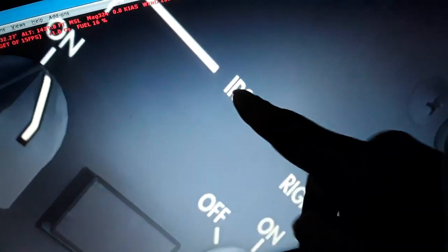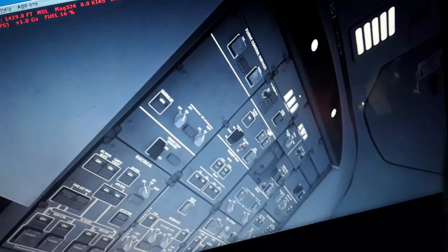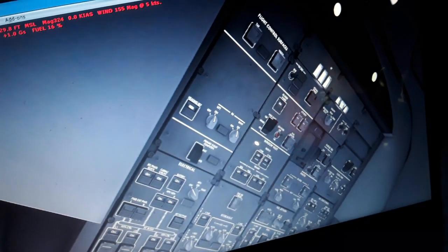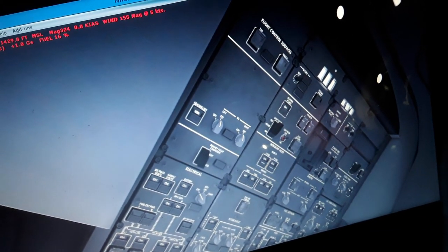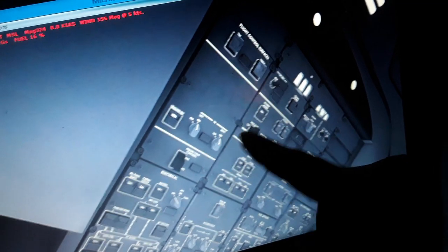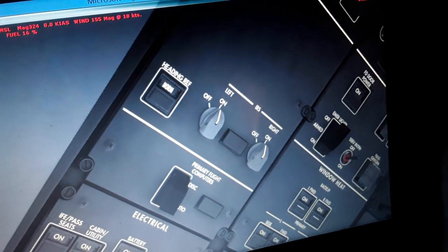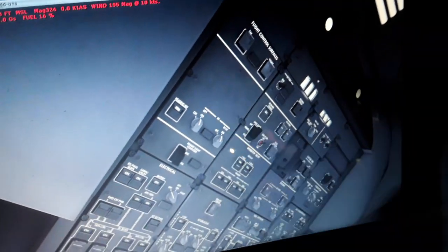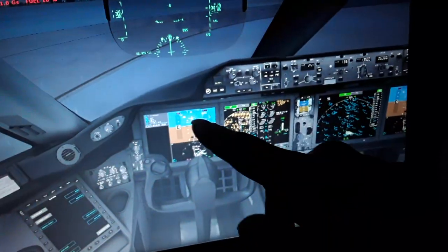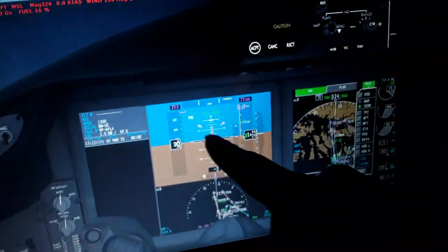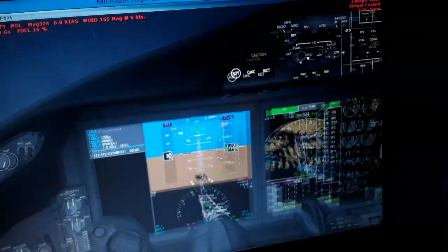So this is inertial reference alignment using laser gyroscopes, the 2 or 3 GPS receivers, the magnetic north pole and the true north pole. We have all the air data, pitot, static and pitot dynamic, the angle of attack of the aircraft as it flies, radio altitude, laser gyroscopic precession and deceleration in flight from the altitude indicators.